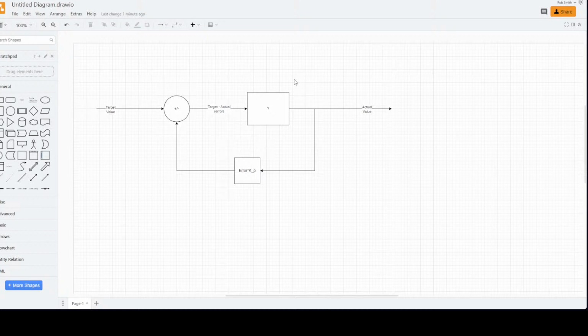But what they would do was have the drive shaft sticking out the front or the back of the engine. They'd weld this massive plate onto it at a 90-degree angle on a known distance, and they had literally a $10,000 sledgehammer, because that sledgehammer had A, very clear center of gravity markings, and B, was extremely carefully machined to be a very specific mass. And using high-speed video, they'd smash that hammer into the plate. It would drive force into the drive shaft and turn the engine a little bit. By measuring the vibrations of the plate, and how much energy was put into it by the speed and momentum of the sledgehammer, they could back calculate a model of the motor. It would be an approximation, of course.